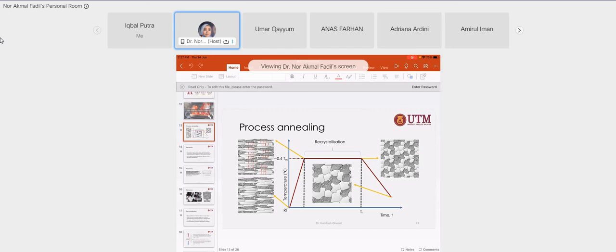Okay, so that microstructure is strong, but equiaxed microstructure is soft. So we don't allow the recrystallization. In my experience with the company, we conduct the temperature similar to annealing temperature, but sometimes we adjust a bit, maybe not 0.4, maybe less than 0.4 of the melting temperature. We conduct, let's say, 0.38, or 38%, or 35% of the melting temperature, and at that particular temperature it will produce